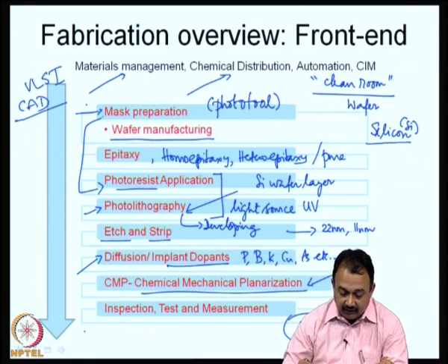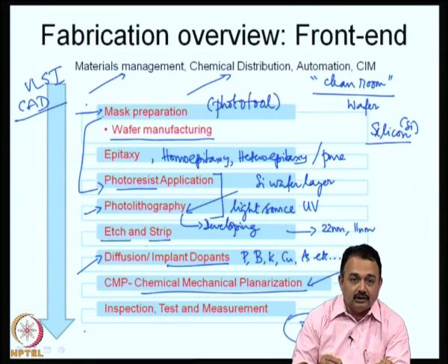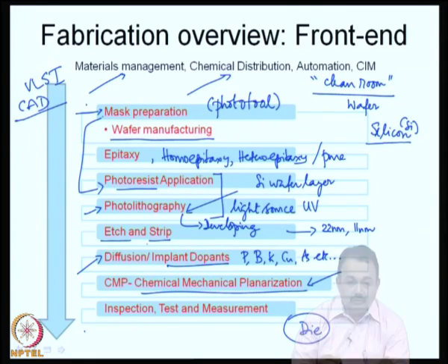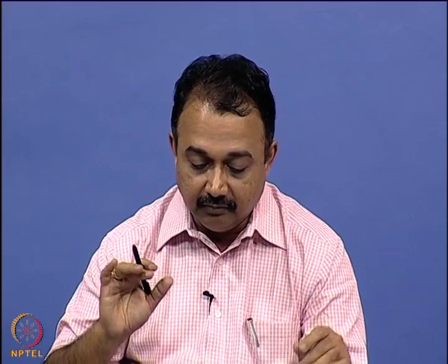So, inspection at every stage of these processes which I have mentioned is very important. You have to qualify at every stage. Finally, the wafer is inspected and electrical test is done, and certain measurements pertaining to the nets that are generated in the design have to be verified. So, this gives you a complete picture about what processes you can expect in the front end process.